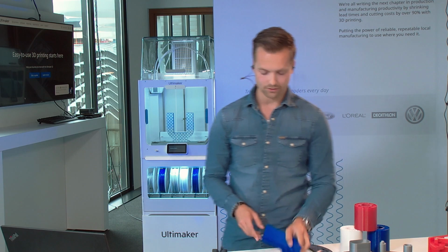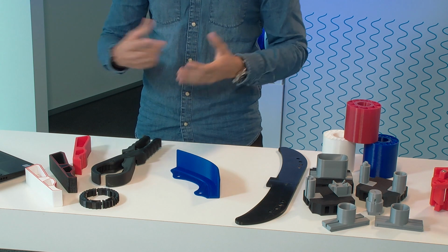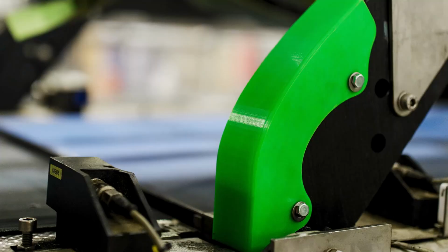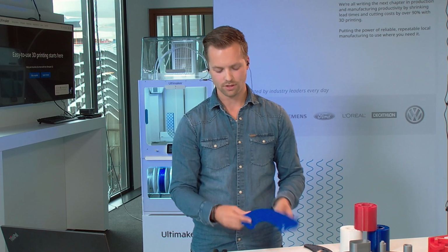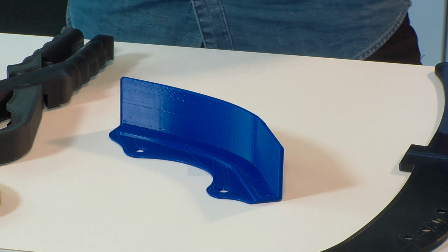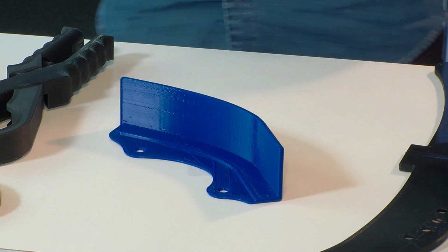Another application I would like to share with you is when people are doing maintenance, they need to crawl in a machine to access certain points of the machine. And in some cases, a chain is not covered well enough. There's grease and there's movement. So we would like also to create a safer working environment there, and therefore we created this chain cover. It's a really simple part, you can print it really easily, and basically this protects the operator from getting hurt by this chain, for the sharp edges for example, and also protects the grease on the chain from collecting dust. So something as easy as a chain cover can also be easily 3D printable.